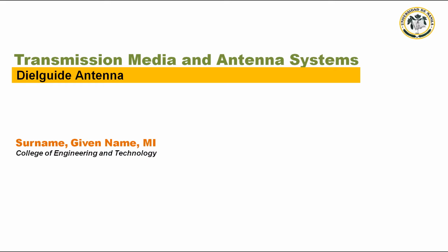Communications antenna designers continually strive to increase antenna efficiency, or for low-noise receivers, maximize the antenna gain-to-noise ratio. The ultimate goal, of course, is a uniformly illuminated aperture with no spillover. Dielguides are dielectric guiding structures or subreflectors. These guiding structures utilize the phenomenon of total internal reflection, which can be effected at a dielectric-air interface, to reduce spillover and provide more uniform illumination.